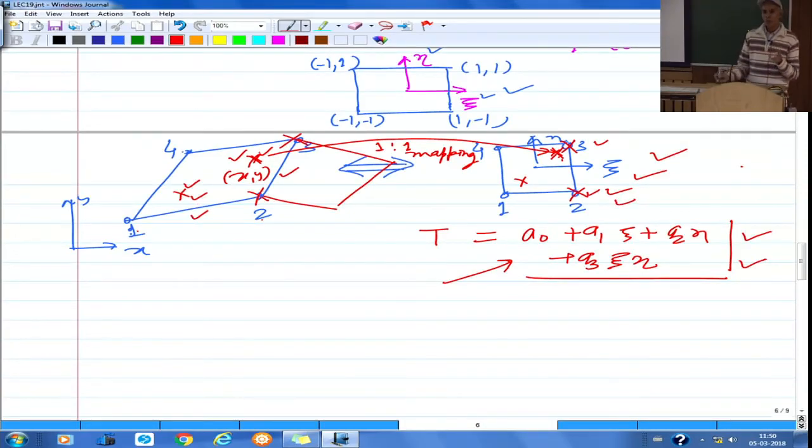If you use higher order interpolation for coordinates and lower order interpolation for the field variable, it is known as superparametric formulation. If the same order of interpolation is used for both x, y and temperature, or the field variables, then it is known as isoparametric finite element formulation.